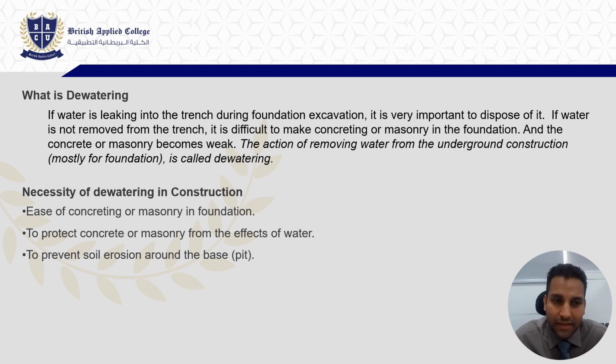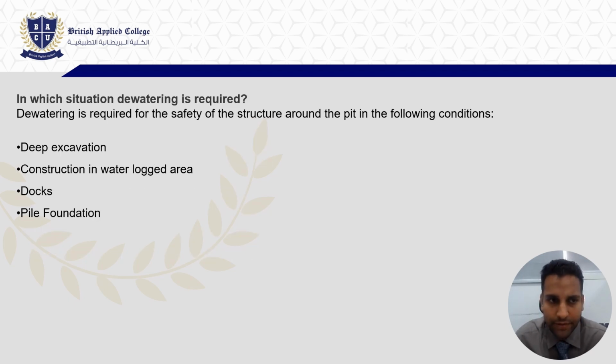Now, what is the necessity of doing dewatering in construction? It eases the concreting process for your foundation. It protects the concrete from the effect of water, and also prevents the erosion of the soil, right? All this is really important while constructing, so dewatering plays a vital role. Now, in which situations is dewatering required? As I have told you, in waterlogged areas, deep excavation, dock, and pile foundation, dewatering is really important.